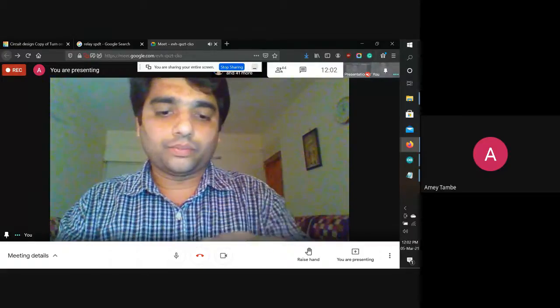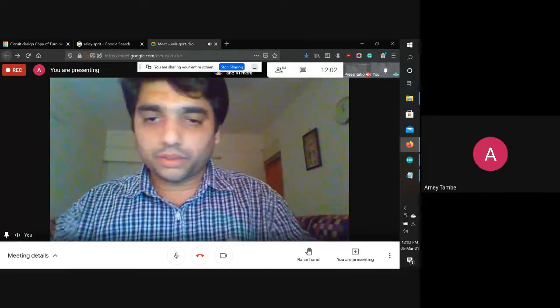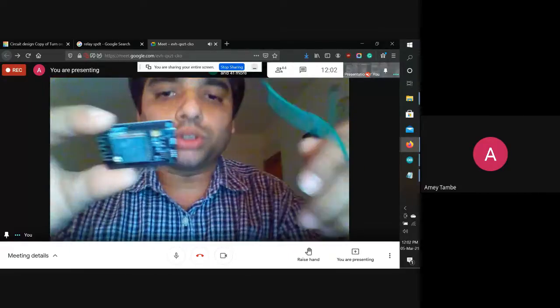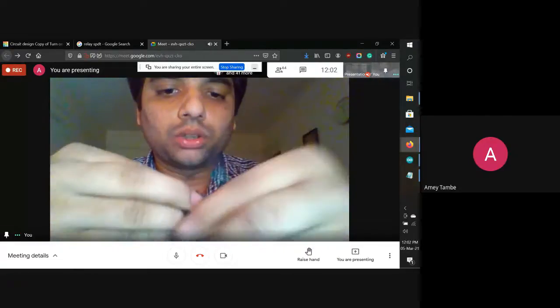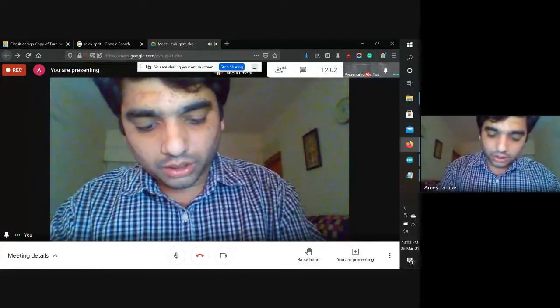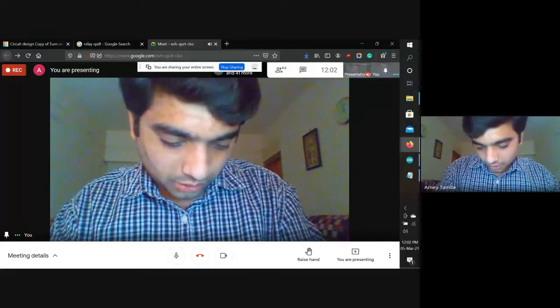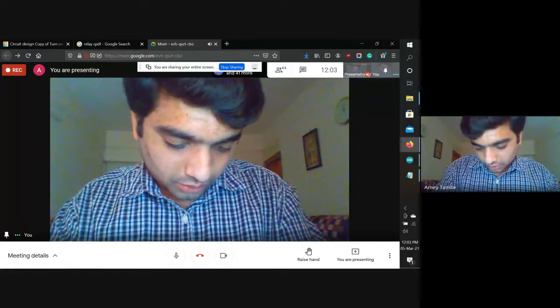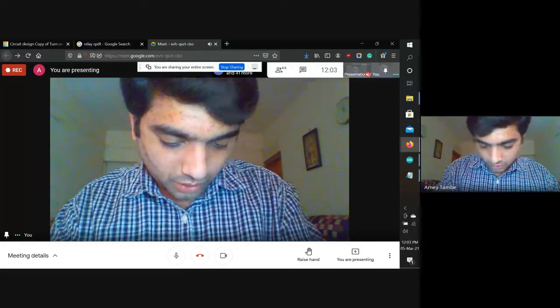that is done. Now the most important part on the ESP32-CAM: you need to put the ESP32 into booting mode. How can we do that? For that we'll require ground and the IO0 pin to be attached. Okay, so here it is.